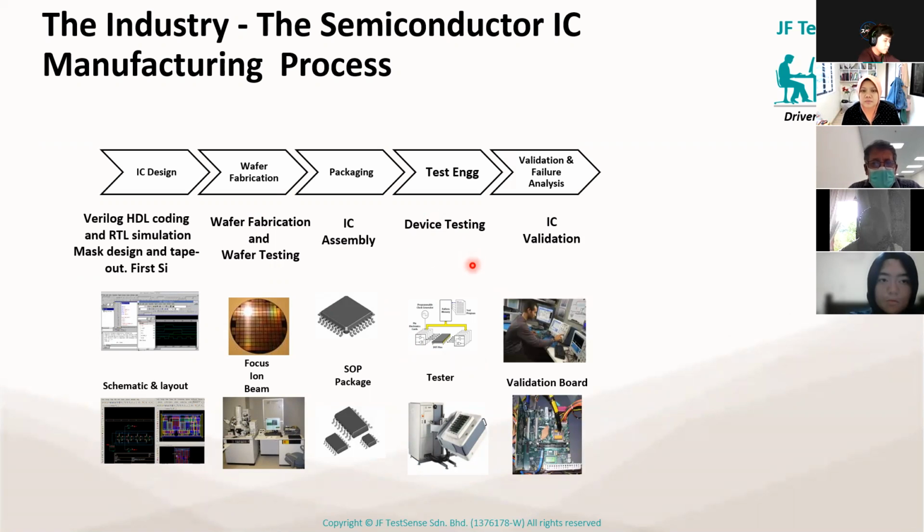So after testing, you will obviously get good parts, that means parts that meet the datasheet requirement, and parts that fall out. Fall out means they don't meet the datasheet electrical specs. Then at that stage, those fallouts are checked out and validated as genuine, or they need to be checked out very thoroughly to make sure it's not a design problem.